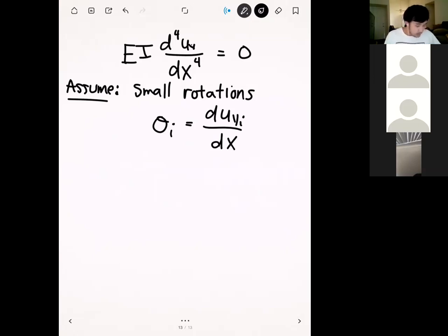Okay. And so these are basically going to be our governing equations for the beam. I'm not going to run through the entire derivation because that's a lecture in itself, but I will give you the highlights and the big picture ideas. The biggest picture idea brings us back to the interpretation of what the stiffness matrix actually represents. Remember, the stiffness matrix represents the relationship between the nodal loads, the forces and the moments, and the corresponding displacements.